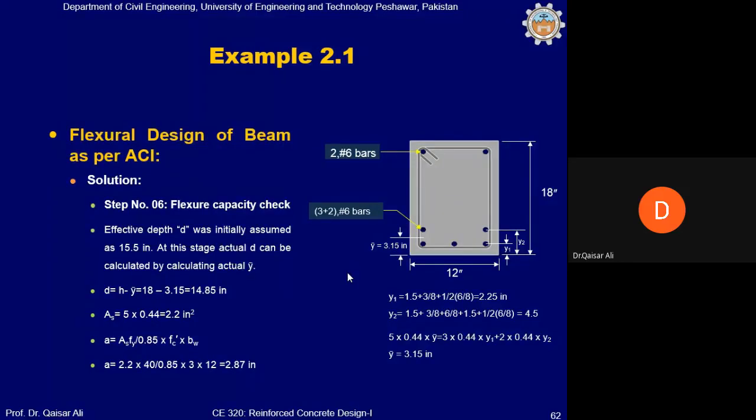लेकिन प्रोबेबिलिटी है, ज़रूरी नहीं है कि 10,000 बीम आप डिज़ाइन करेंगे तो उसमें ज़रूर एक फेल हो सकता है, 1 लाख बीम भी बनाए उसमें भी एक फेल ना हो। और वो प्रोबेबिलिटी ऑफ फेलियर इस तरह निकली हुई है कि हमने इसमें ये एजम्पशन की है कि हमारा स्टील का सरिया जो है वो ग्रेड 40 होगा तो उसका FY हमेशा 40 आएगा, 60 का। तो ये पॉसिबल है कि 10,000 केसों में किसी एक जगह पर स्टील की यील्ड स्ट्रेंथ जो है 60 के बजाय 58 हो या 52 हो या 53 हो, ये हो सकता है। इस तरह कंक्रीट की स्ट्रेंथ FC प्राइम की 3,000 की बजाय 2,000 हो।